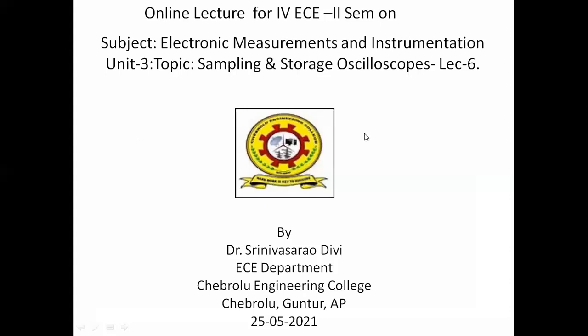That selection of the different signals is applied to the vertical amplifier and to the vertical deflection plates. So the dual trace oscilloscope traces the two signals with a single vertical amplifier,